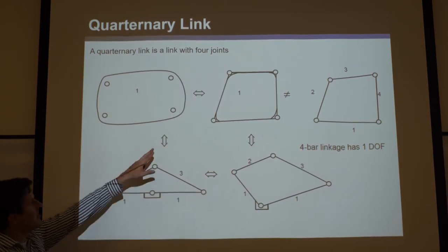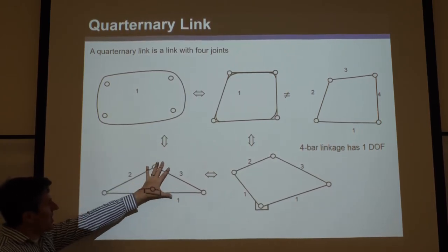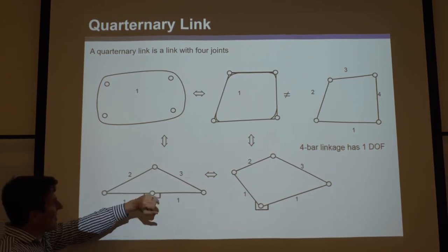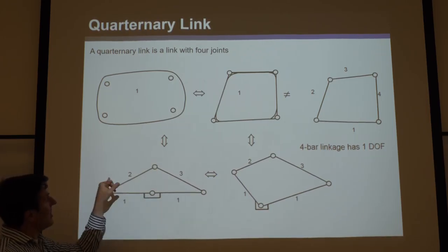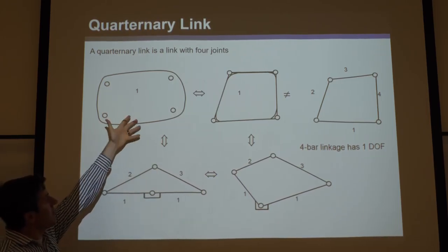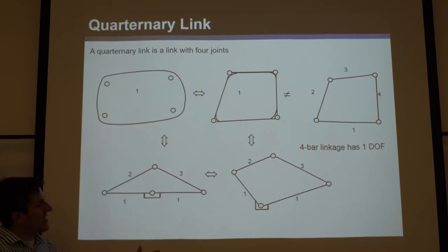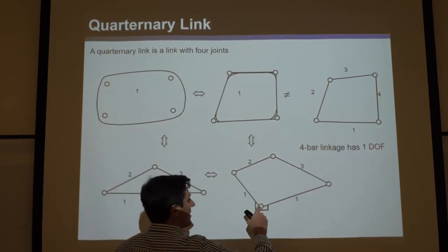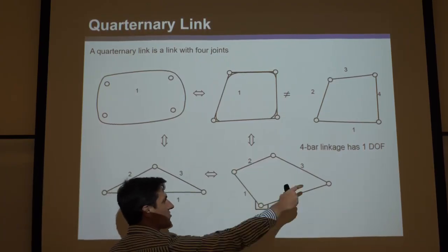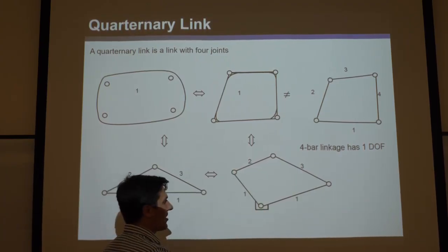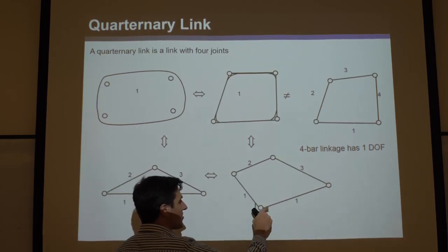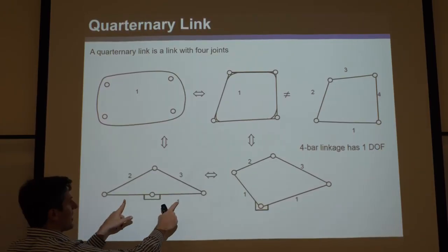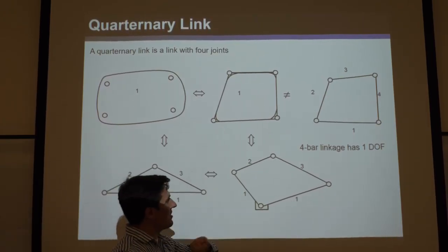The reason there's this equal sign is because this would have no degrees of freedom. It would act as if it's a rigid link with 4 points on it, and so this would be kinematically equivalent to a quaternary link. And same with this. The only difference between this and this is that we gave this an angle. So you see, you can bridge things that aren't straight if you need to draw an angle there. But if there's a square or a circle or a bridge thing or hatched-in thing, that means this is one and the same thing. And notice these are both labeled 1, which means they're the same link and they're ground.